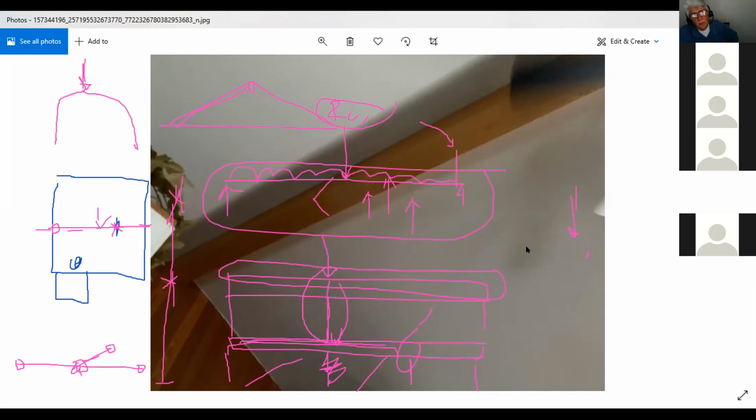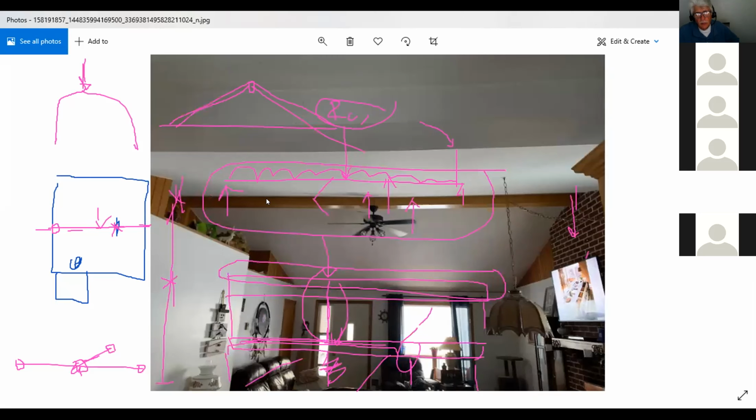But what's happening is the rafters are being supported by this thing. So at least here you have a good idea. Go back to the picture where you see the beam from the side, you see? So here you have a good idea that all the roof load is going there, and on this part of the floor you have absolutely nothing, because that's where your beam is, it's right here. Yeah. So now we know that here we have nothing because it goes from there to there.